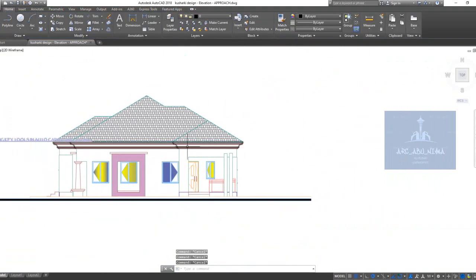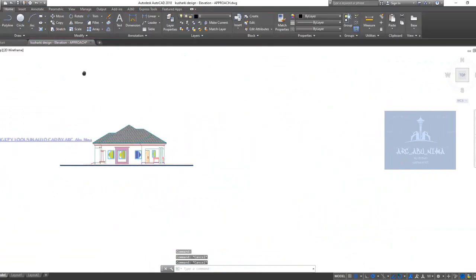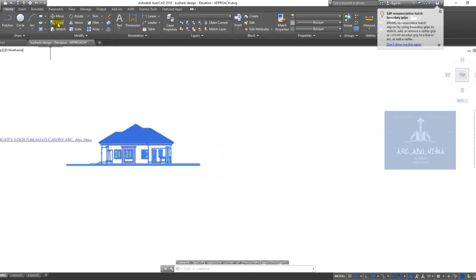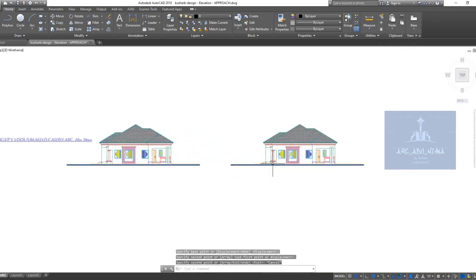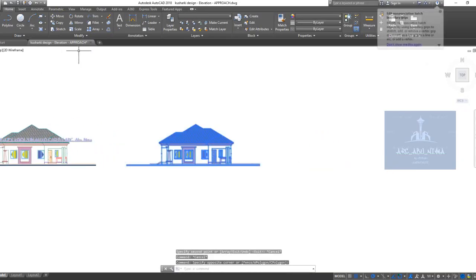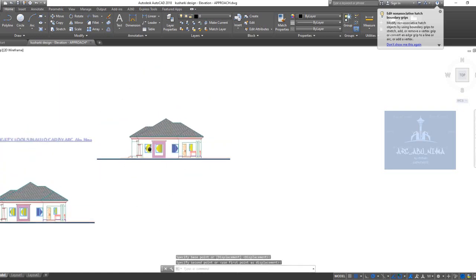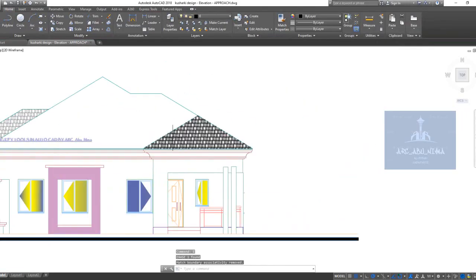Okay, so let me demonstrate that for the angle now. I would like to use the tool. Also, one of the tools we'll discuss is the move and the copy. So let me copy now. You select, then you copy. This is the copy tool, or CO is copy. To move, you use M to move. So I'll delete this